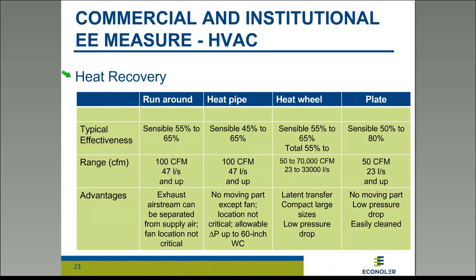Another application is heat recovery that has been applied with success in different buildings, and there are different types of technology available. The simple run-around coil, so it's two coils with a glycol system that circulates glycol between the two coils. This one is especially interesting in retrofit applications when you don't have proximity between the exhaust air and the inlet air. So with this kind of system, it's almost irrelevant where the ventilation systems are located. You can install a heat recovery system. Their main disadvantage is that they are not so efficient.